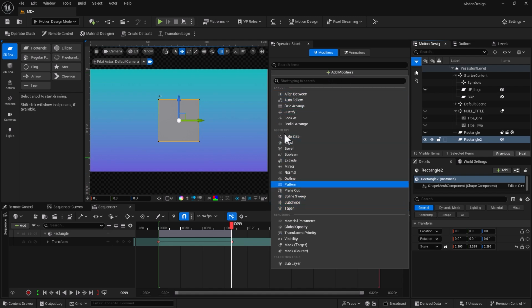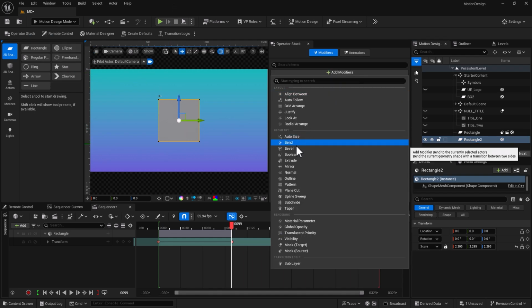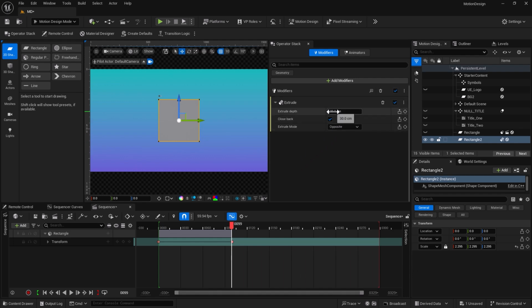So all you see in here reminds me of the modeling tool, as I said before. So you select, you go into extrude, and you start extruding your object. Now if I turn this, you can see I'm applying extrude to that object. You can close the back, or you don't want to close the back, that's totally fine. So that is open. You can fill hole and put the cap and close the object if you want. The rest of them work exactly the same.